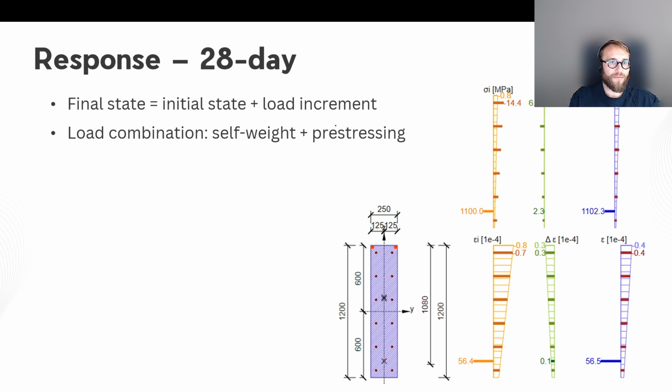So once I put just the self-weight or the dead load plus the pre-stressing, I'm able to display three levels of the states. I would say this is like an initial state that you're able to account for. This is a linear stress, a normal force and bending moment, that consists of the self weight plus pre-stressing.